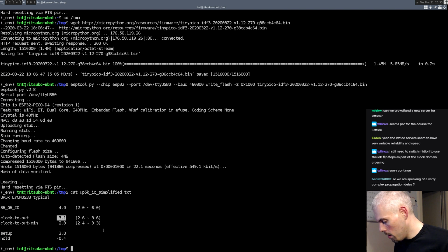Okay, so I think that's pretty much setting all the setup for the example. And so we're going to look at talking to SPI flash. Actually, no, we're going to look at talking to both SPI flash and, at the same time, a PSRAM. They're both going to be on the same SPI bus, which means that we need to meet the timing for both with one circuit, right? The same circuit has to meet the timing for both the flash and the PSRAM.